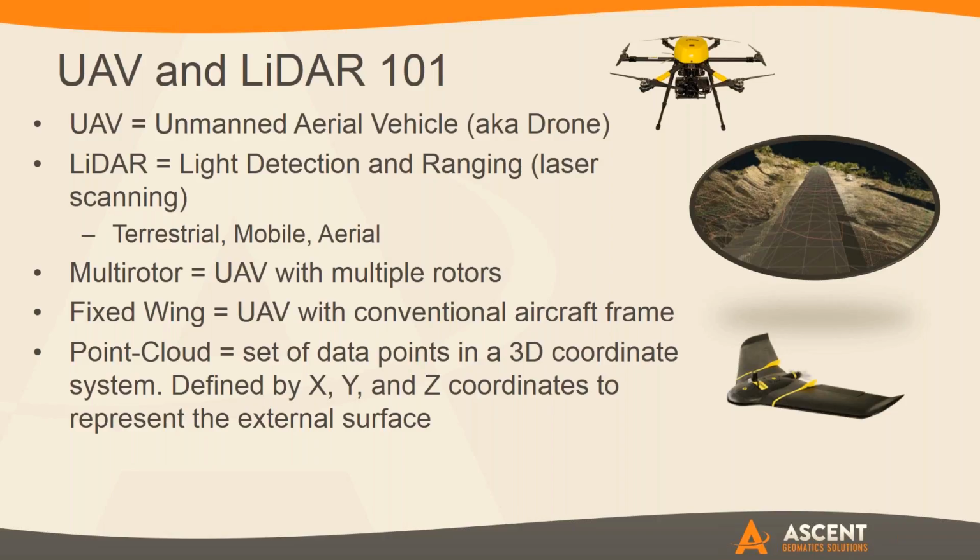This is very similar to sonar or radar, where it's going to send out a pulse and it's going to get a return. There's different types of LiDAR. Terrestrial LiDAR, which we basically will mount on top of a tripod, and there's different ways in which we would use that. Mobile LiDAR, where we're collecting data at 45, 50 miles an hour. And then even aerial LiDAR, where we're actually using a UAV, or potentially even could be just a conventional plane.